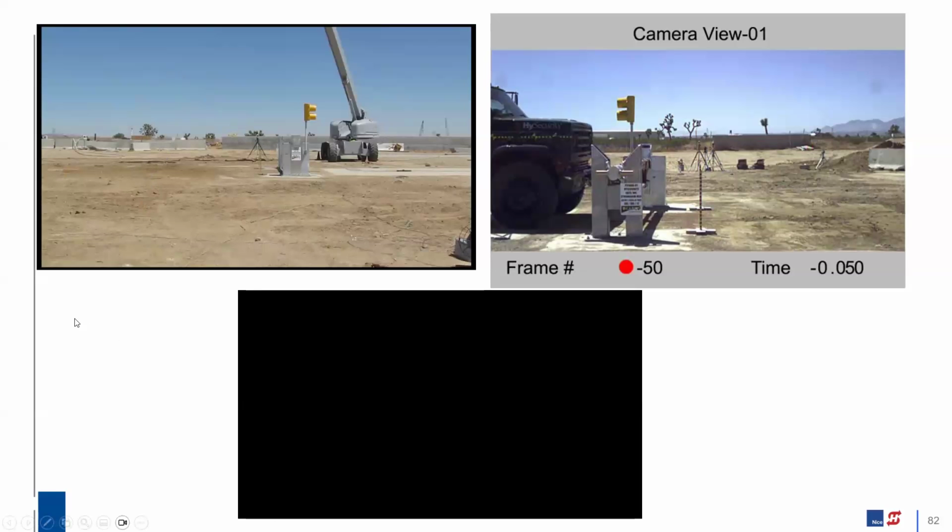After that M designation, then there's the penetration rating. So P1 is typically past the perimeter up to the 1 meter mark. P2 is the 1 meter mark up to like 28 feet, and P3 is in the next county. Remember, in these scenarios, we're only concerned with the payload on the truck bed. It used to be the bumper broke the perimeter, but now we're worried about the payload on the truck bed breaking the perimeter.